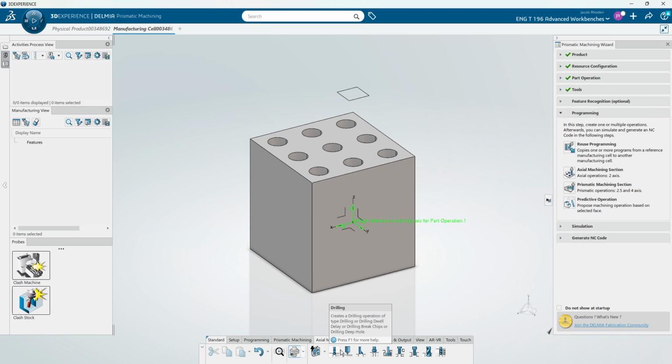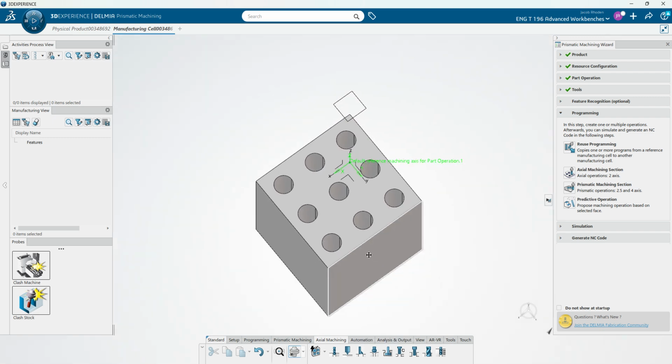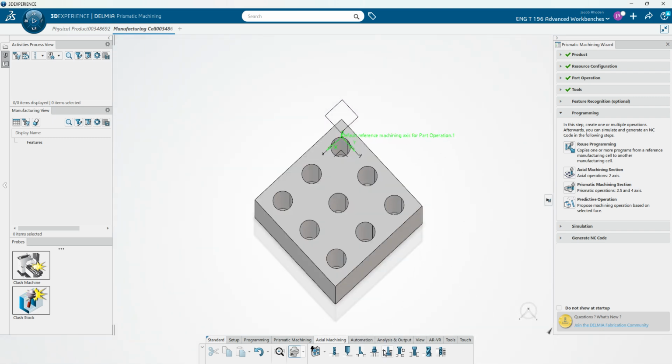And then deep hole drilling, which is just another process. And then spot drilling, which does a little initial spot in the part, so that then when you have a drill, especially if you're going through a deeper hole, it won't let it wander on the surface, so you can get a more precise placement of that hole. Boring, so we have boring or boring spindle, stopper back boring. So these are all different ways to make sure that once you've drilled a hole, you can take a boring bar or a boring head and have it go around the inside of that hole to bring it to a very, very tight tolerance. So you can bring that within 1,000ths, you can bring that within half a thousandths, just depending on your boring bar.